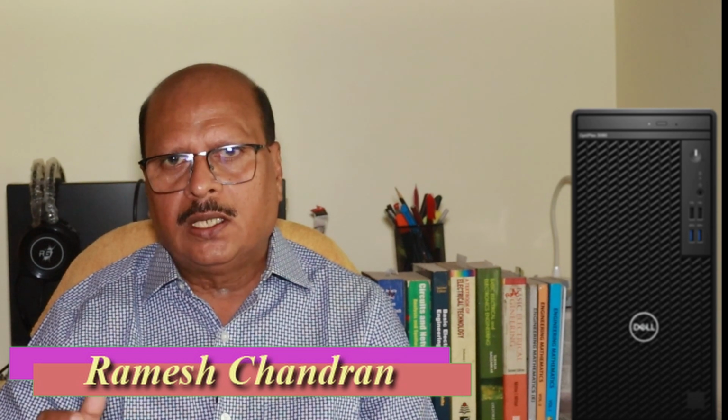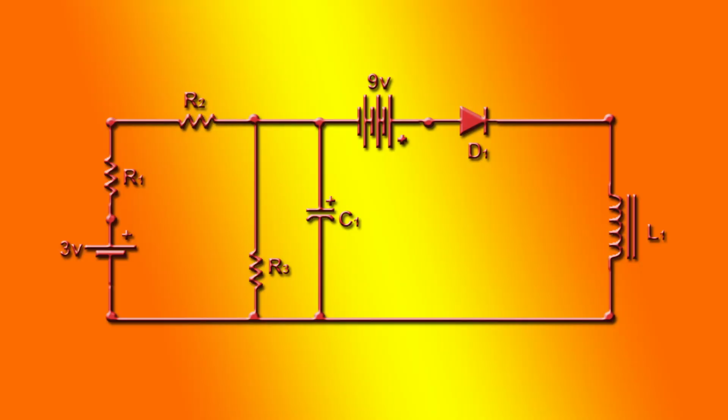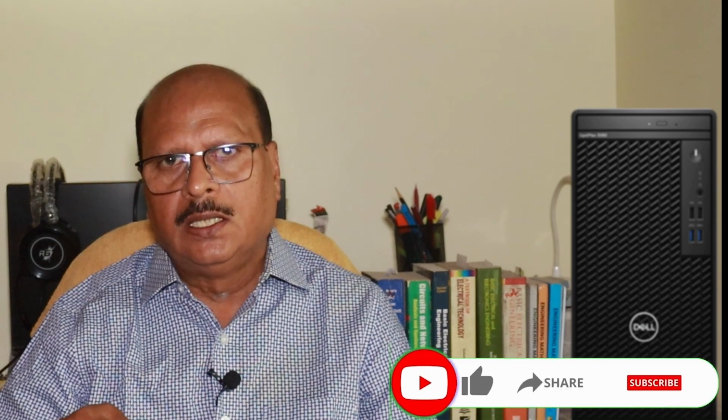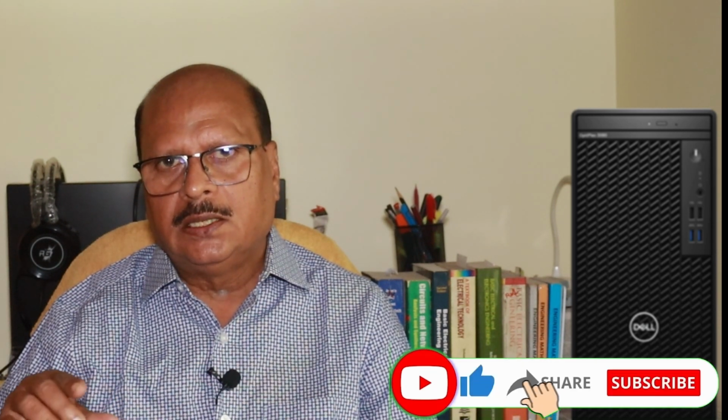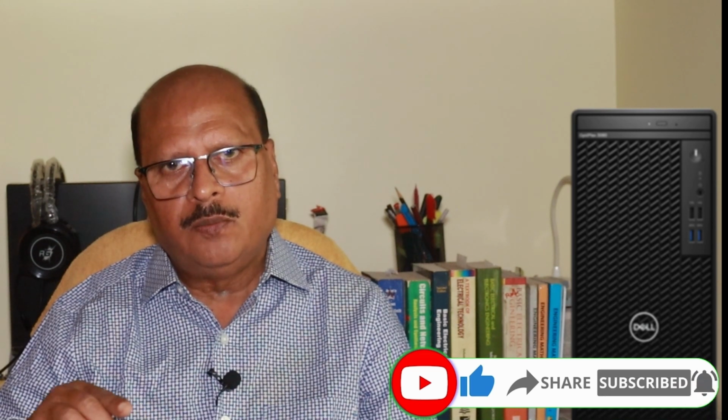through the core. We know that in electric circuits there will be voltage or current sources and components like resistors, capacitors, inductors, etc., which may be connected in series, parallel, or a combination of both as per the requirement of the circuits. Similarly, in magnetic circuits also there will be magnetic materials having different reluctances which are connected in series, parallel, or a combination of both as per the requirement.